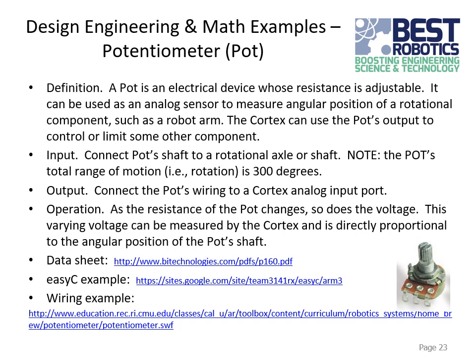It can also be useful if you want to automate some tasks so that a driver doesn't have to manually do it. So let's say you want to have a button that automatically rotates your arm 90 degrees. Well, if you have a potentiometer there that's connected to the axis, then you could see what the current angle is, and then take control of the motor and turn it until it gets to the new angle that you want, and then tell it to stop. And so doing automated things like that can make the driving a lot easier for your drivers, and that can help you do better in the competition. It can make things quicker.